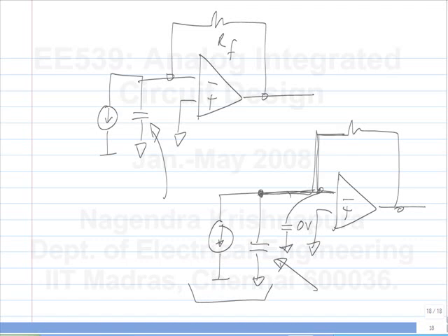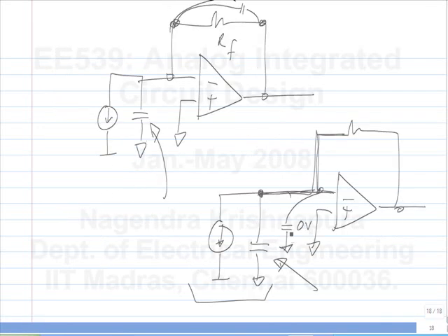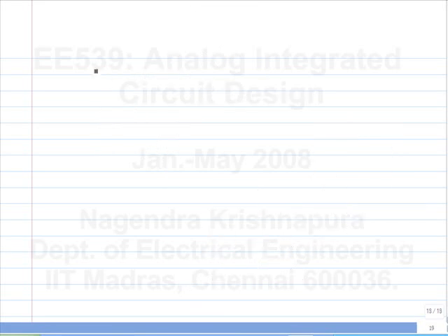So in our analysis, we have to plug in a different value, not just the photodiode's capacitance value. In light of this, what's the difference between this circuit and this way of introducing the 0? Here, the op amp capacitance appears at this point. In the other circuits that we saw, the op amp capacitance appears with CD, so it modifies the value of CD. That means it will affect our bandwidth in some way, but it will not affect the stability.